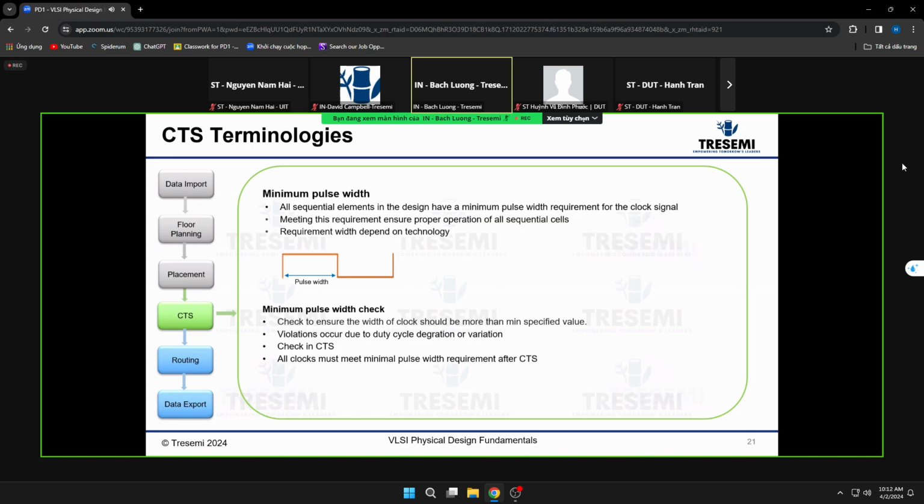Global skew doesn't impact timing between two blocks, but still affects the whole design. Yeah, the whole design, but also think about the system level, one level up. If you have one short, one long, you're going to have a hard time closing timing at the system level, and also think about the overall performance of this SoC.